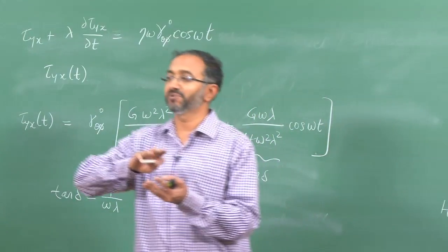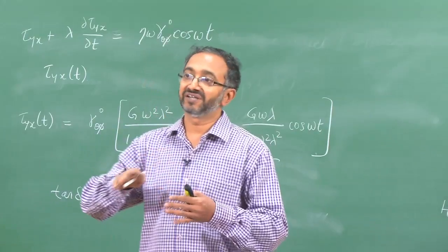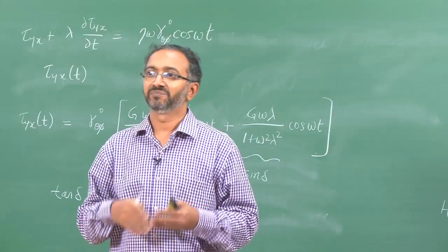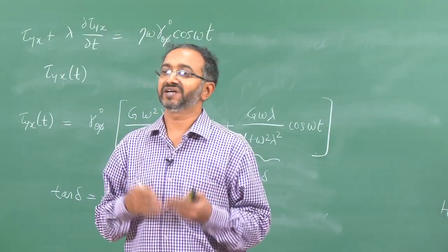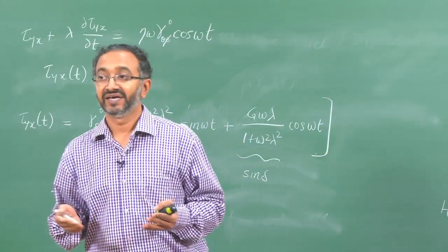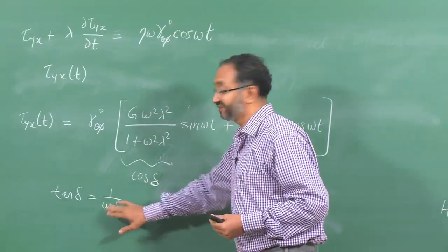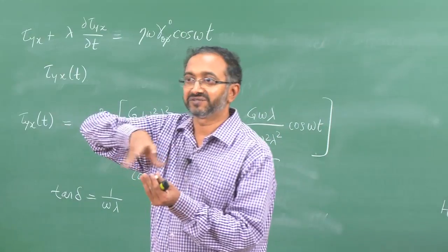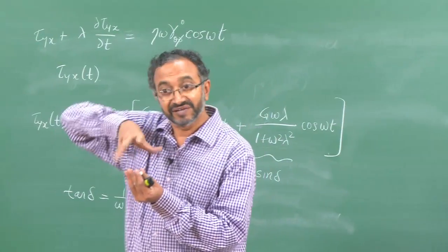When frequency is very small, we are allowing the material enough time to respond, therefore all relaxation processes can happen, and the material will show dissipative and viscous response. If we apply very high frequency, we are not giving the material enough time to respond, because we are providing the mechanical stimulus very fast.